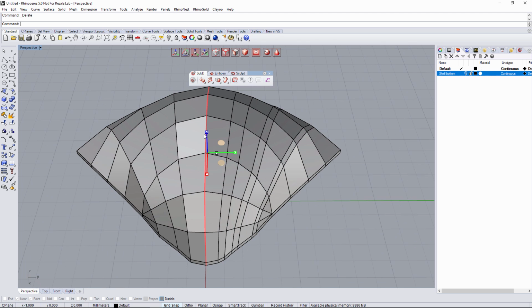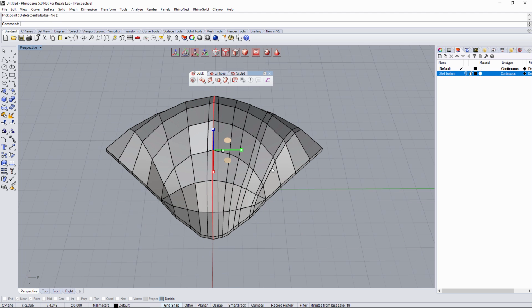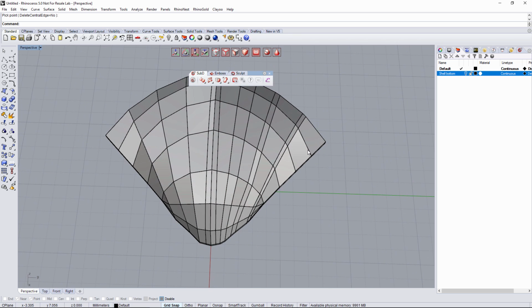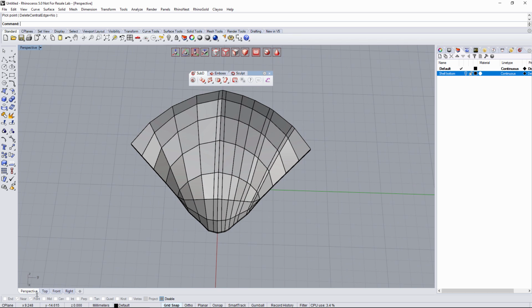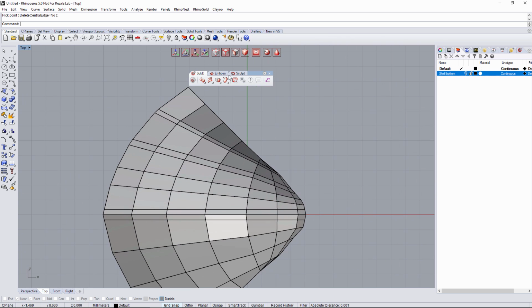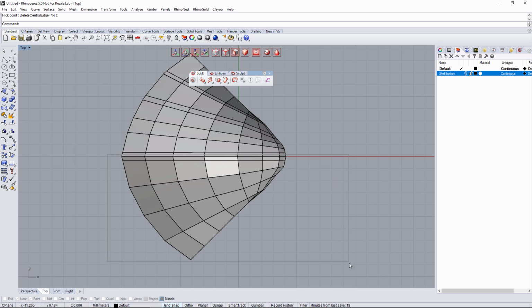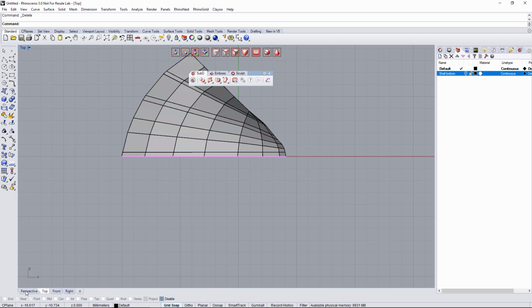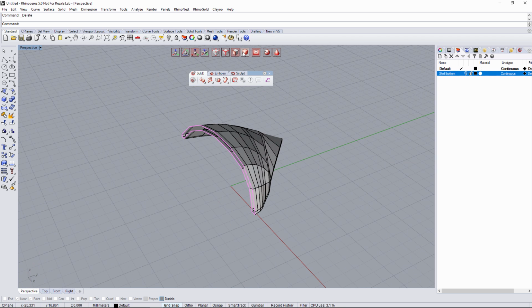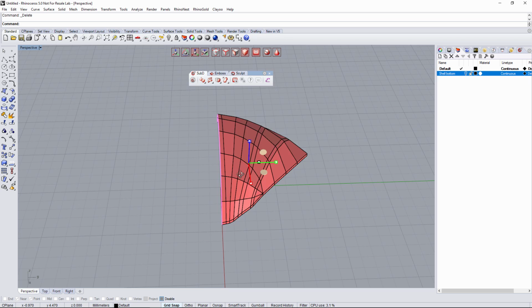And here on the central one, what I'm gonna use is the split sides. Okay, and I'm gonna do the split sides like that. Okay, something like this. And I don't want to delete that because I want to create the symmetrical axis in here, so I don't have to create this part multiple times. So from the top view, I'm gonna grab the faces, and I'm gonna select all of them, one of the half, and delete. Okay, perfect. And what I'm gonna do now is I'm gonna select the entire object.